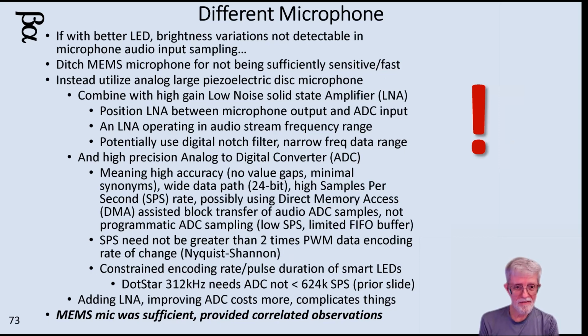And I could use a different microphone. A microphone without that filtering on the front end would pick up lower levels, and I could put my own amplifier on it and drive it higher. But that's a lot of extra complication and cost, and I picked up the signal just fine with the microphone that I used. So if somebody really wanted to get serious about it, they could do these kinds of things. The parts aren't that expensive.